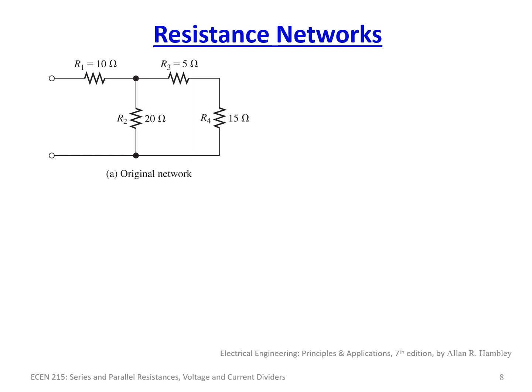So here we have a resistance network, and the homework is going to be a lot of this kind of stuff. You're going to have different resistance networks, and it's going to ask you to give the equivalent resistance value of the network. This is more of a geometry question than anything. So we're taking a look at this resistive circuit. The first thing to do to boil the circuit down to an equivalent is to find all of the series resistors and add them up, and then all of the parallel resistances and do the parallel, and so on and so forth. Then you can go back and forth between the two.